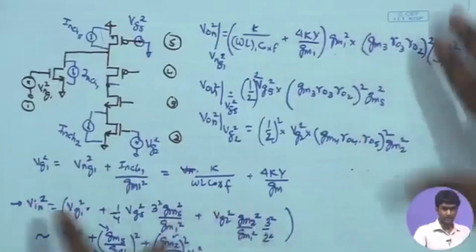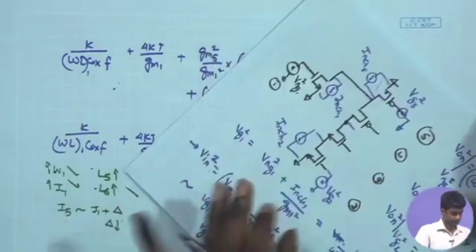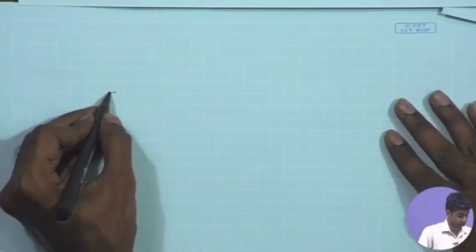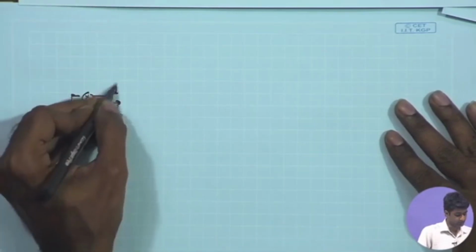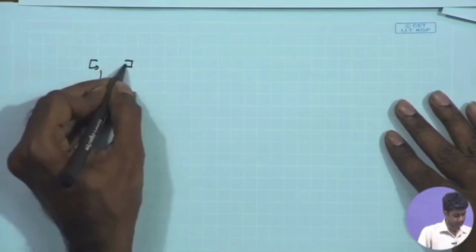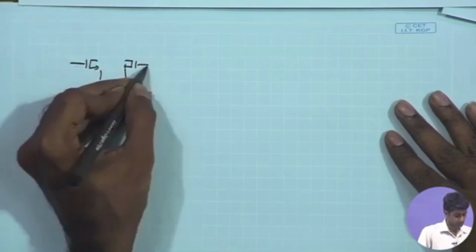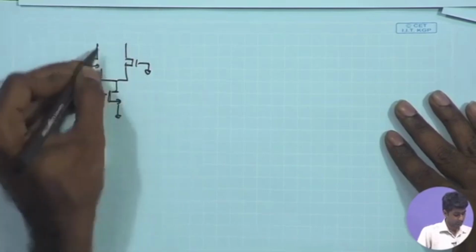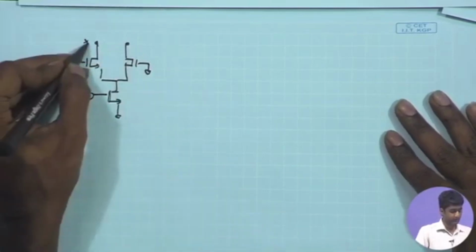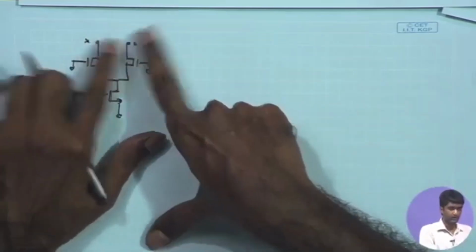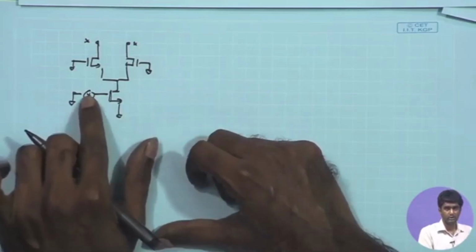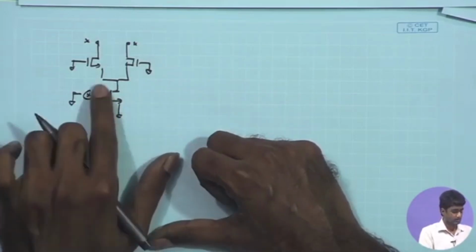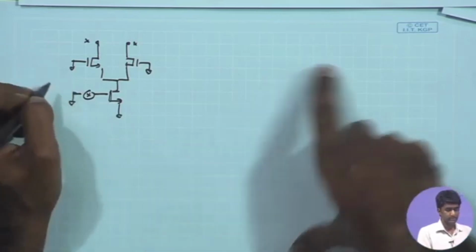So if you are looking at the tail current source, whatever noise is produced by the tail current source, it is going up the two paths, and is going to result in equivalent voltages at both the nodes, and in a fully differential operation it will be cancelled out. Therefore, we do not worry so much about the tail current noise contribution. So this is one point that we need to keep in mind.